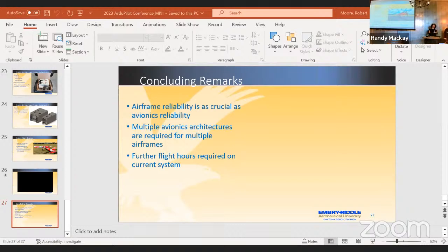The 2 ArduPilot controllers, are they identical, or are they different in sensors and architecture? If we run 2 of them, the 2 will be the same, but there's a bunch of different sensor architectures within the one. There's 5 IMUs in the one. I will say they're all InvenSense. But we have 5 different sensors in there.